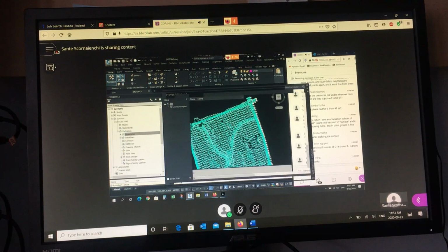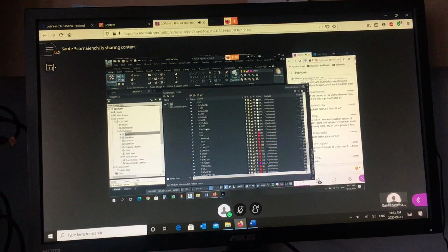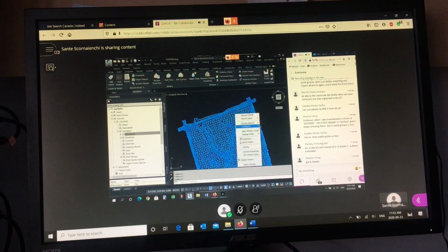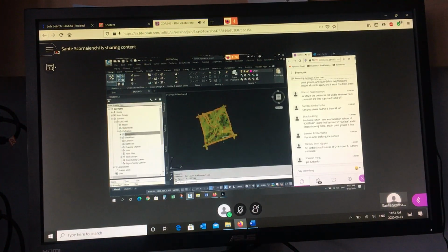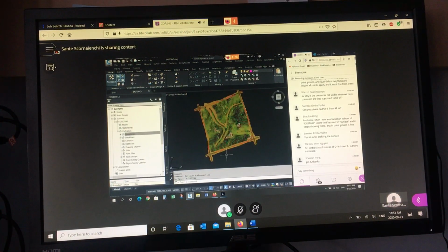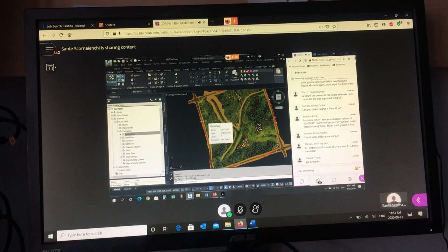And then for presentation, again, you're going to turn off all the layers except the ones that represent the surfacing and the trees. So that and that. And this one I want to see. And then this has to have a style. Contours, you have to create the style for contours. I'll give you the parameters for that. And that's generally what your drawing should look like. And then again, everything has a color for the line type, which I'm not doing. Plus all of the labels, right?